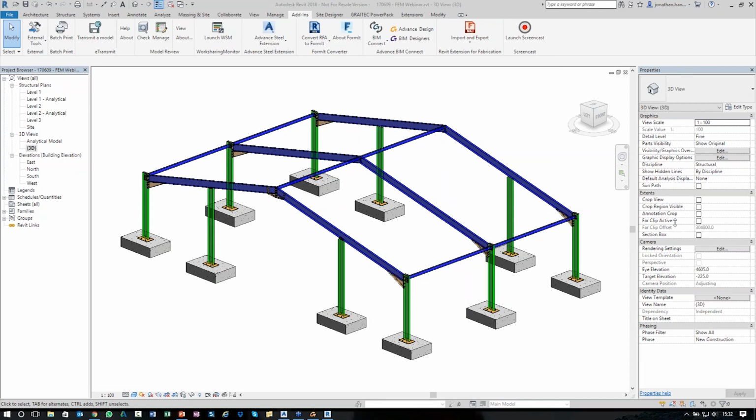Again, it all depends on if you're going to use Revit as a structural and detailing package. Obviously there are limitations as to what you can do in terms of how quickly you can add multiple connections and grouping connections together and having the same connection update with master joints and stuff like that. That's better in Advanced Steel. And in Revit, it's still sort of individual elements.